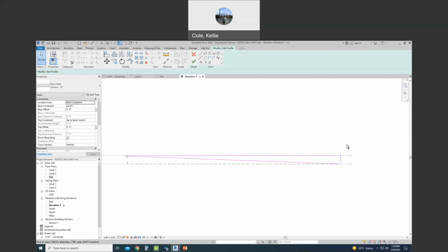So the funny thing, again, I'm in a command in Revit. The top ribbon is that turquoise color. I have to tell Revit, check yes, I want out of this command, or no X, and it will just completely erase what I've done. So anytime I'm editing walls, these have to be a complete form.